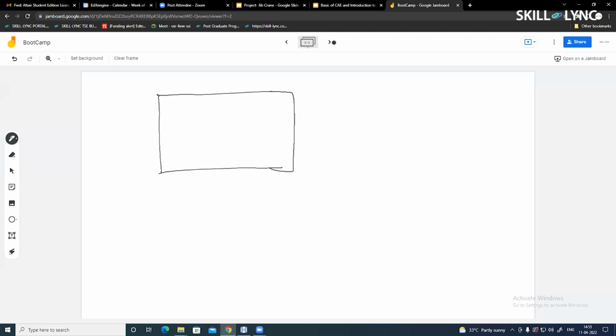Because, as I already mentioned, in FEA we have a domain which we convert into a discretized domain, change into equations, and compute using a numerical technique. So I'll have a set of equations to come up with for this problem, and the number of equations will be the number of nodes or points I have in the problem.